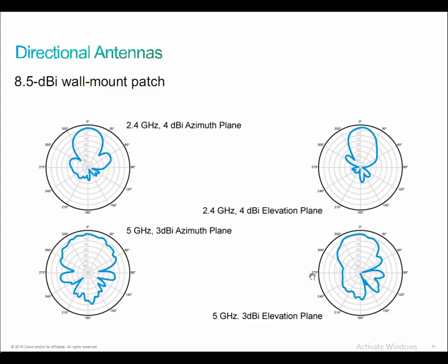So the shape of the antenna coverage pattern shows that it follows one floor coverage logic, meaning that we don't have any coverage above and below the antenna, but we don't have a very large vertical range either, or even a horizontal range behind the patch. Only in front of the patch we have a large horizontal range.